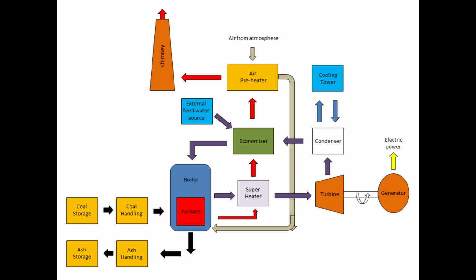11. Cooling tower. It is a tower which contains cold water. Cold water circulates to the condenser for the cooling of the residual steam from the turbine. 12. Chimney. It is used to release the hot burnt gases or smoke from the furnace to the environment at an appropriate height. The height of the tower is very high such that it can easily throw the smoke and exhaust gases at the appropriate height, and it cannot affect the population living near the steam power plant. 13. Feed water pump. It is used to transport the feed water to the boiler.